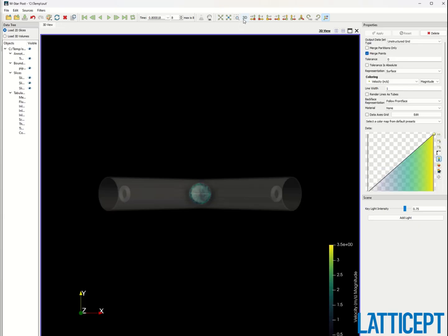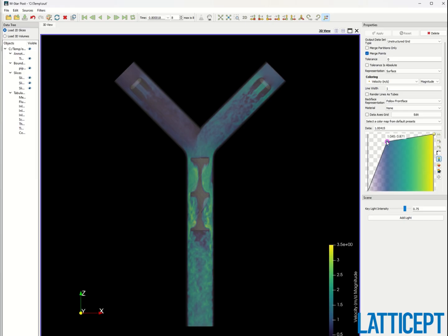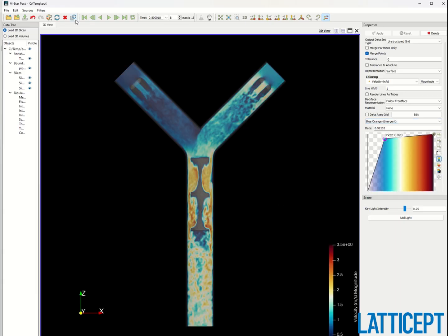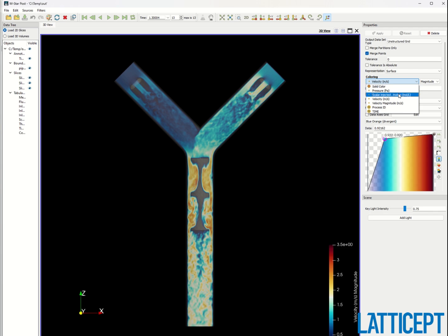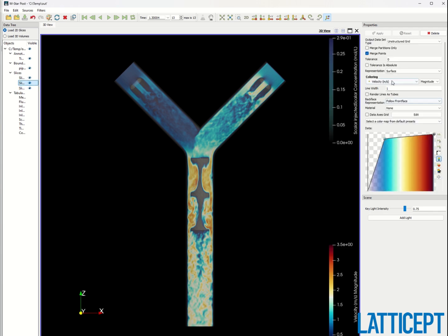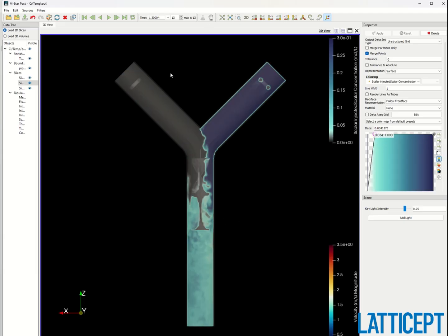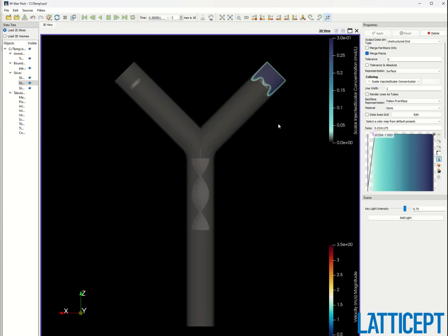Pops up. I'm going to switch to 2D just because it's prettier. Click plus Y. All right, look at this. We've got the turbulator here working. We've come swirling around this. You can see it twisting around this twist element here. Let's change the colors for our directors. Let's go back to the beginning. All right, now let's look at our scalar. See how our scalar looks. Oops, on the wrong slice. I mean, much better. I was looking at it from the wrong direction previously. There we go. But this is obviously much better than it used to be, right?